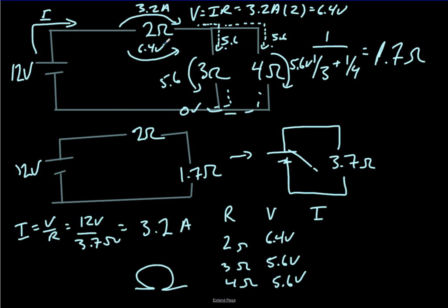If I have a lower current here, do I have the same voltage drop? I don't know. You have to reanalyze the circuit, right? Whatever voltage drop we have here, the remainder falls across here, okay? So yeah, it's all about paring it down and working backwards and sorting each thing out individually in the circuit. And it will take practice, and I'll give you practice. Don't worry. Okay, so current through here, just get her done. 3.2 amps go through there.